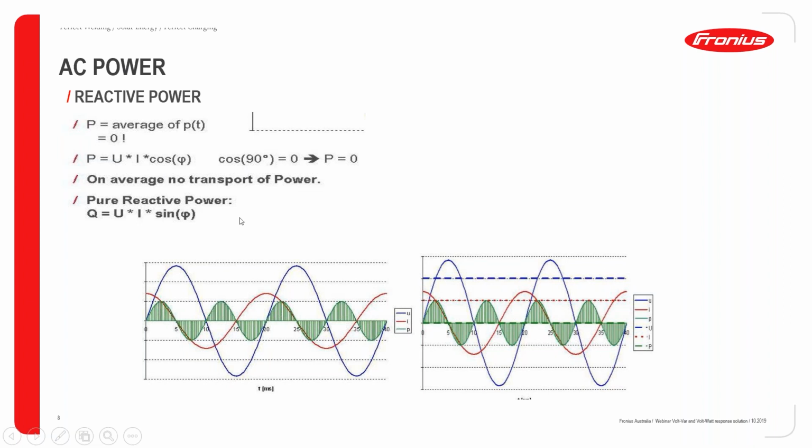Okay, the power factor in commercial buildings ranges from 0.85 to 0.95, lagging or leading in some situations. I just wanted to give you a quick overview of what happens when the power factor angle is 90 degrees. There is no real power flowing through that transmission line. So this is what it shows: power factor at 90 degrees, we have 0 power.